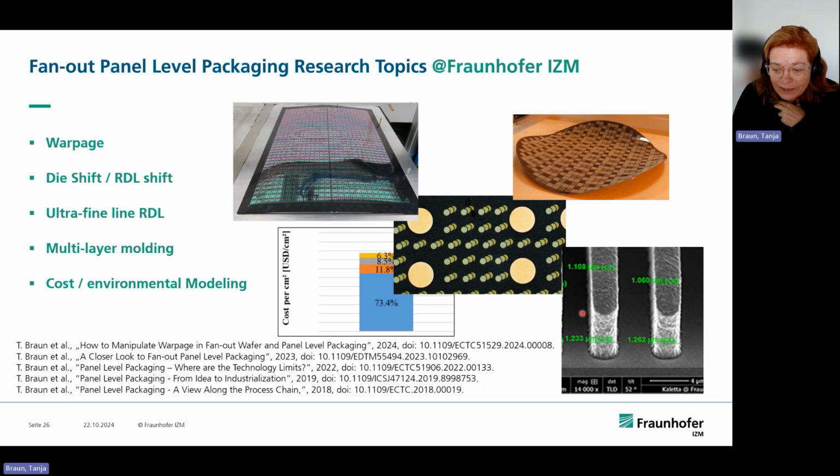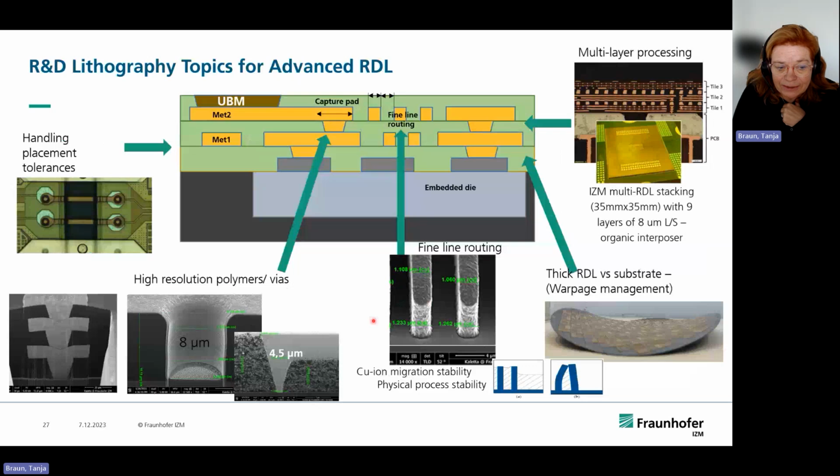Still, how fine a line we must go on the large panel and what is cost effective, also driven by the different applications. I think for RDL we also have to further develop on the panel, especially the stacking of wires, which is highly required. We cannot only shrink the lines and spaces. Of course, we also have to shrink the wires, otherwise it does not make sense. So you see extreme multi-layer stacking. There are a lot of topics for the RDL to further develop.